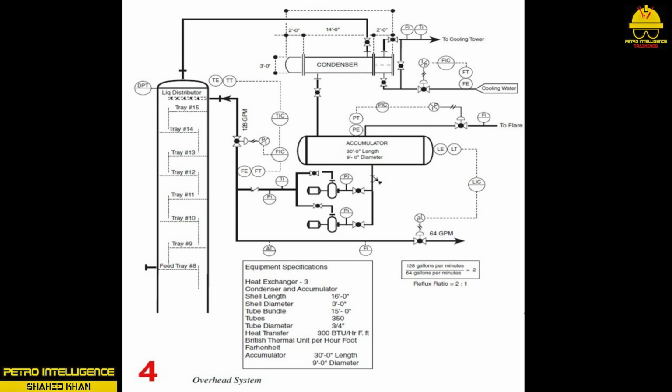The condenser is designed to condense most of the vapor, however, some is used to control system pressure in the vapor cavity above the liquid in the accumulator. This pressure control process literally backs up and controls all of the pressure on each tray in the column, top tray to bottom. The system pressure in the accumulator and the liquid feed temperature, combined with the liquid height above the reflux pump, provide adequate pressure to the suction side of the pump.